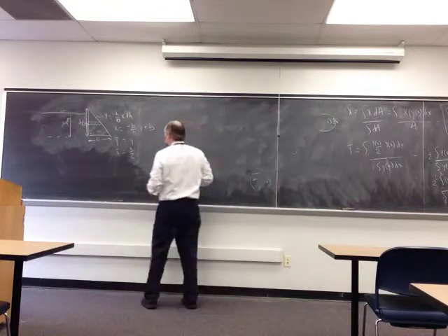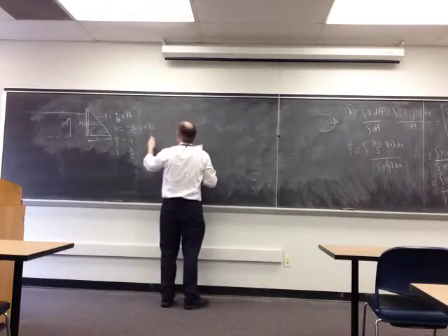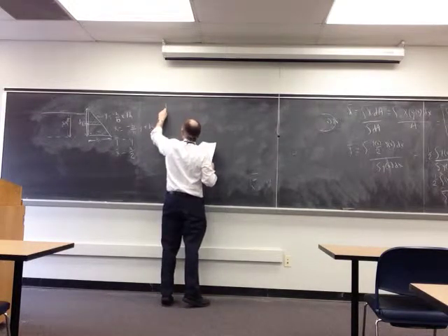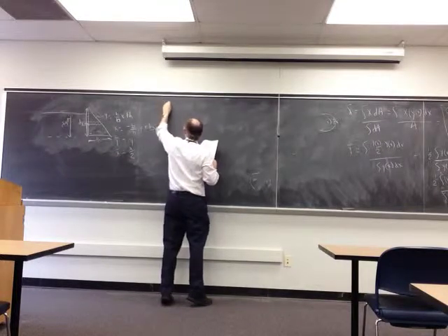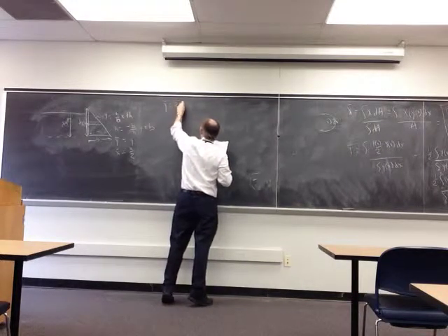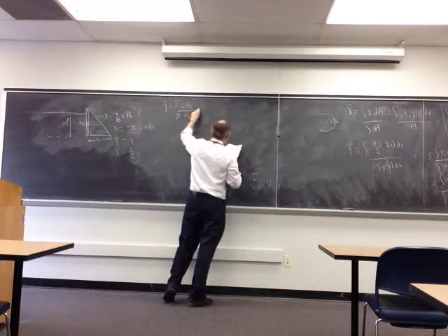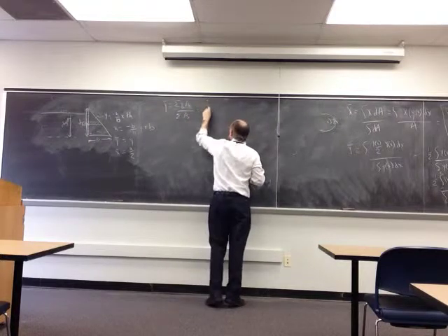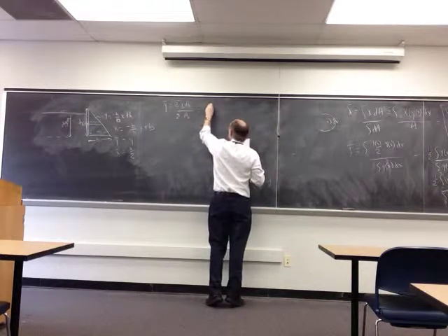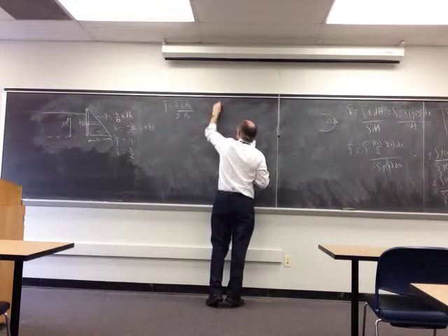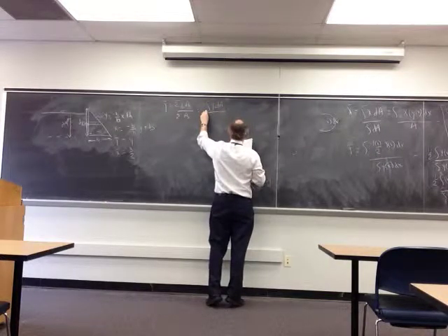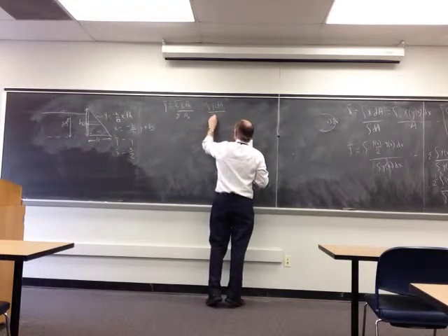And so we go back to the previous equation. It's still the same equation in that y bar is equal to the sum of yi ai over the sum of ai. And that's equal to the integral of y dA over the integral of dA.